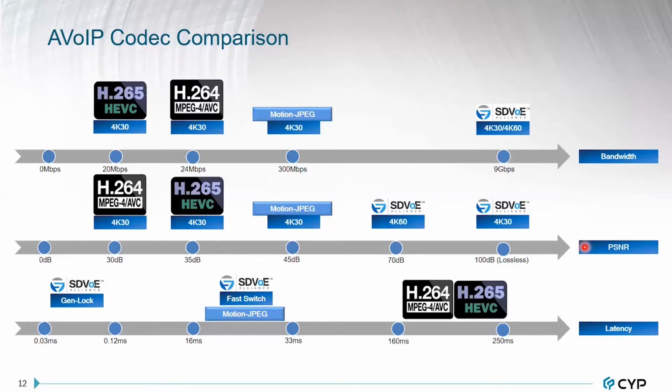When the PSNR is 100 dB, it means that there is no pixel loss. The smaller the value, the greater the loss. It can be seen from this table that the CDM codec has no loss at 4K30. This is because 4K30 can be transmitted at 9 Gbps bandwidth without compression. When the resolution reaches 4K60, there is slight compression and the PSNR is reduced to 70 dB.